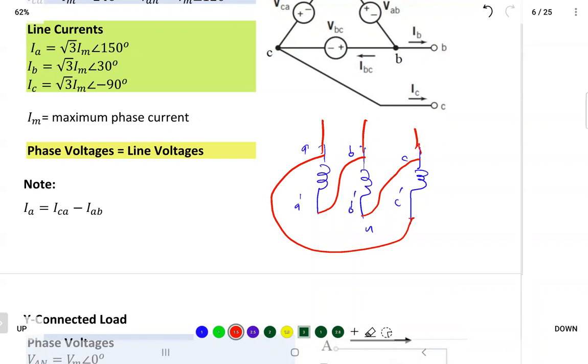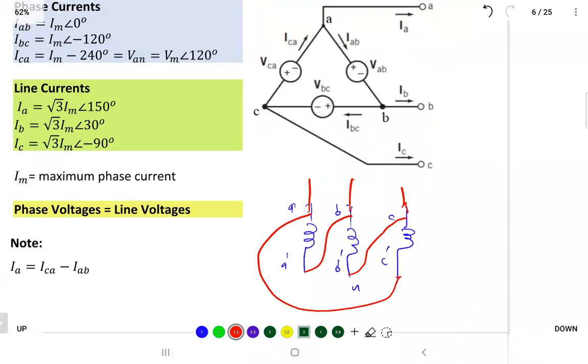Maybe it doesn't matter to you now because everything is already connected, but believe me, we need it. I used to live on a farm for 10 years, and I would get an induction motor, and sometimes you have to connect star and delta. You'll find on the plate when you unscrew the top, you have A dash, B dash, C dash. Sometimes you call it R, X, Y. It doesn't matter, but you have the beginning and the end, and if you understand that, you can change from delta to star this way. I know in the lab it's connected inside, but it's important to know how to connect it. You'll face it. So that's the delta.